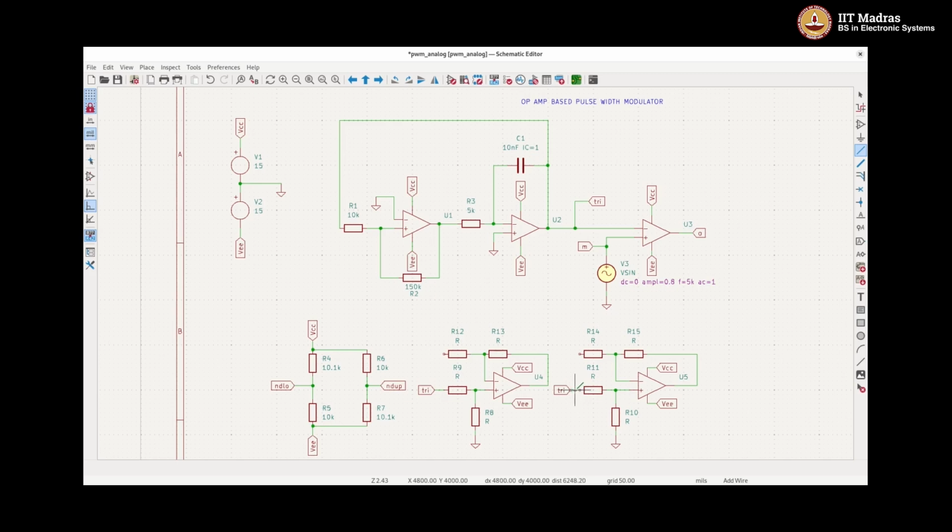So I have connected the triangle waveform to the plus side of the differential amplifier, and now to this I will connect these offsets. So let us say the lower offset, minus offset, I will connect it here, and the offset which is above 0, I will connect it here.